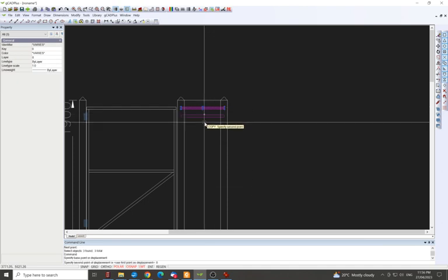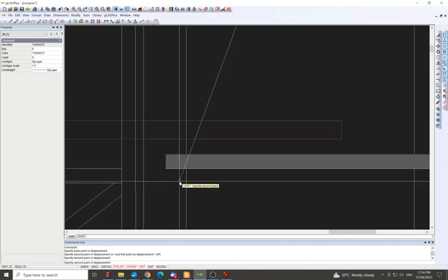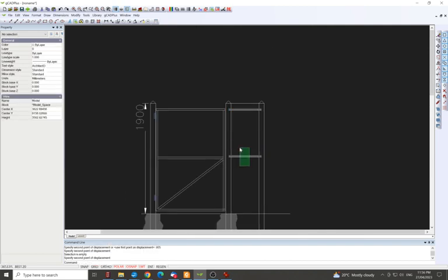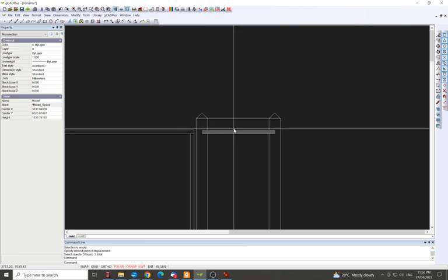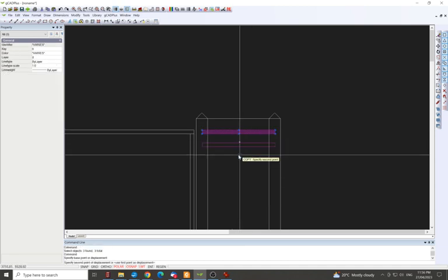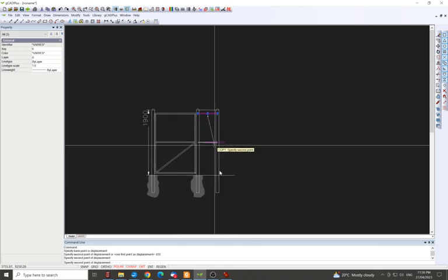If we just type in 805, we're just off, I think. So what we want it to be is 835. Sometimes I'm not sure if it's taking the measurement from this side or that side. So copy that again, not a big problem. Copy, move down, 835, enter, and it's spot on.